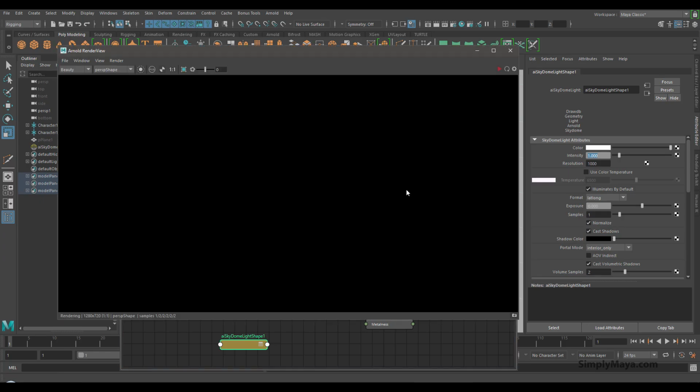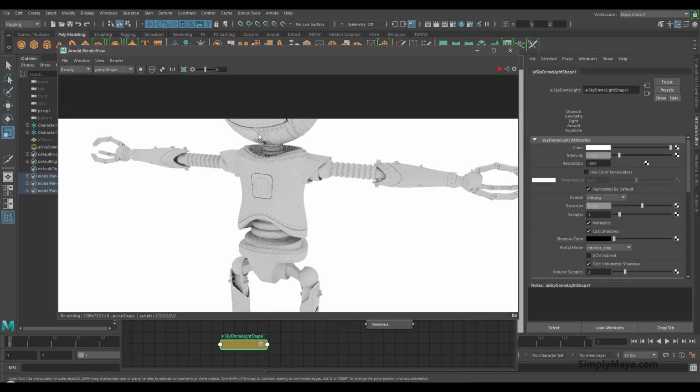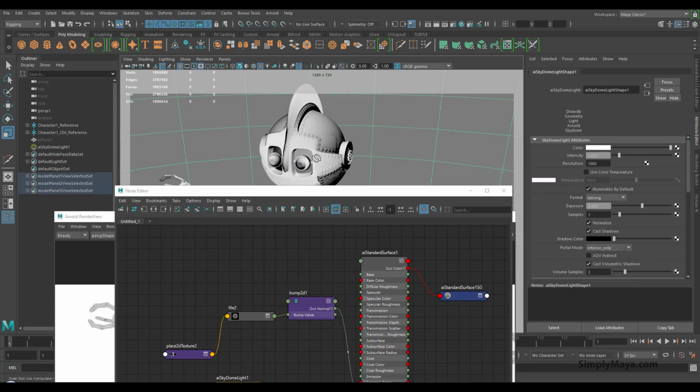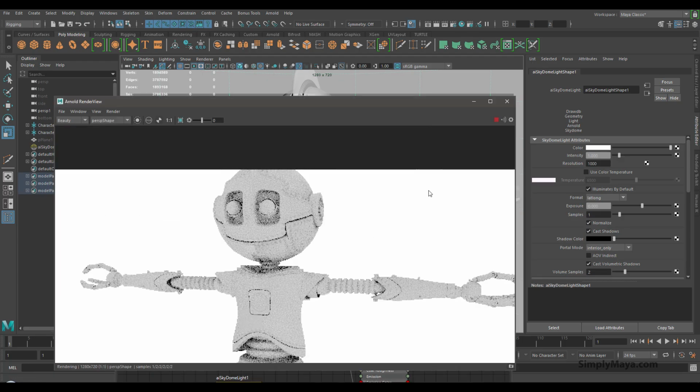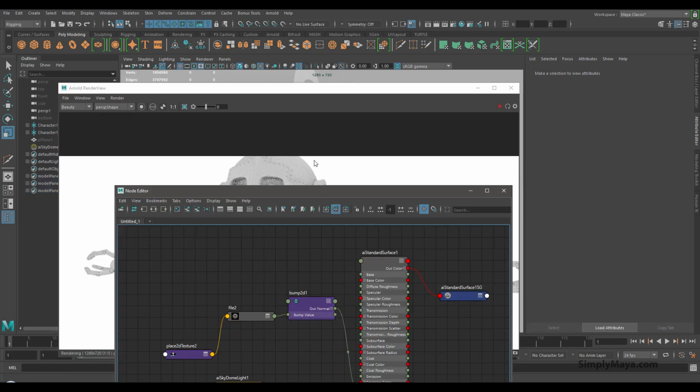I'm just going to show you that this is going to go awfully wrong with the color space set wrong. So you can see here that we do have that banding showing in this view. It's almost correct, and in fact you could be forgiven for not noticing that. It's fairly evident on the viewport, but on the render it looks kind of okay. Let me just do this again, and this should show you that we do have some areas here that are just not right. I mean, this should not have a line here. This should not be darker than this. There is something definitely up here. So we know what that is because we've already discussed it. It's the color space that's set wrong.